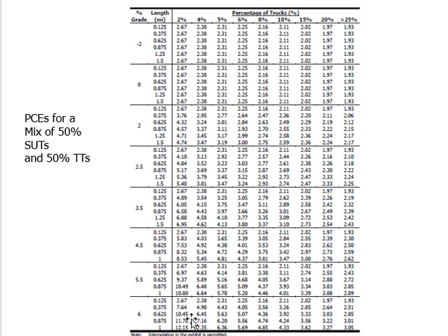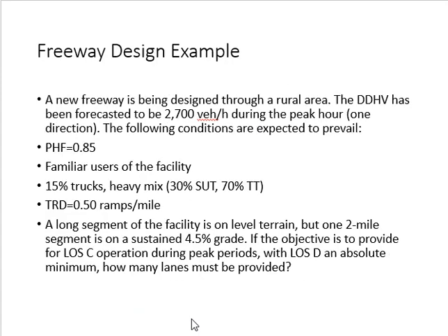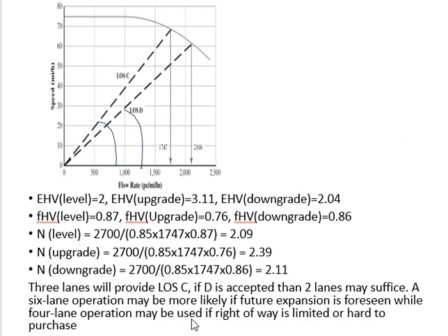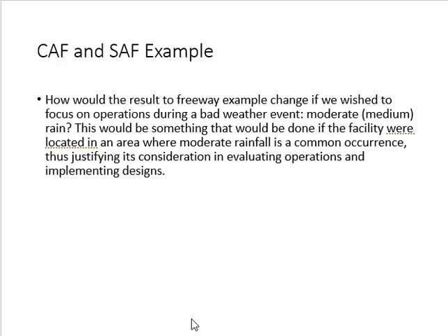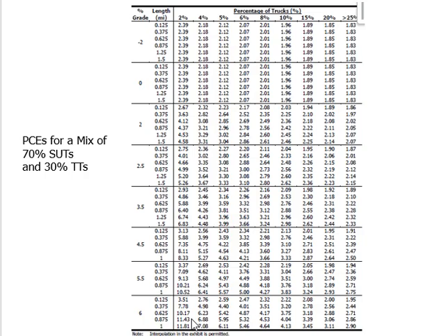Now to use one of these tables, I must know the mix of heavy vehicles. What did they say about the mix of heavy vehicles in the question? What type of mix do I have? Standard. Standard is this one. Single unit trucks are more, trailer trucks are less. Single unit trucks are normally higher than the trailer trucks. So I pick a factor from here.